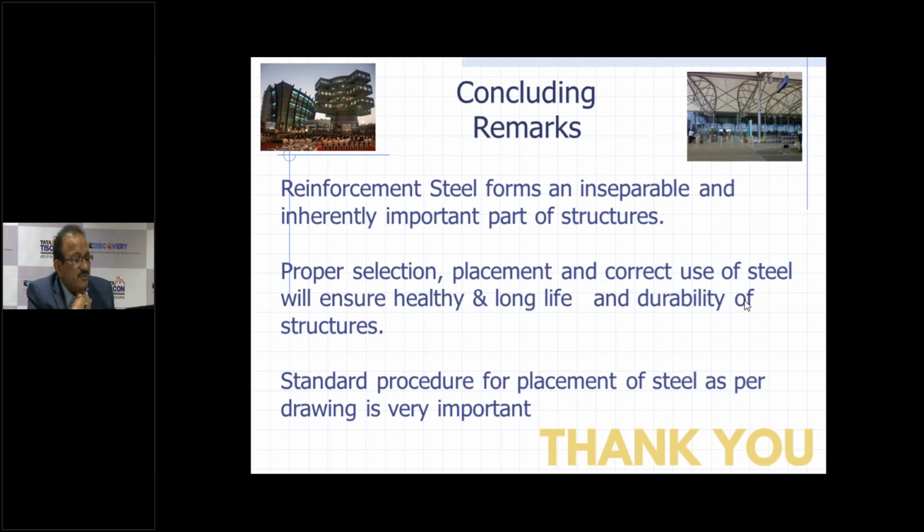Good pictures of actual construction site. Okay, plastic cover blocks are not good anymore. You are right. We must go with factory made concrete cover blocks. This is what Mr. Hemant Vadaikar is saying. Yes, you are absolutely right.